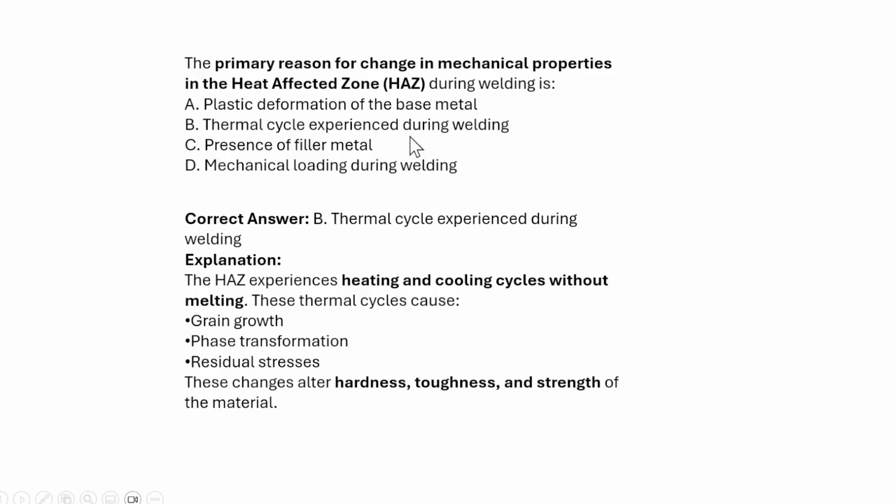Thermal cycling, yes, the heat dissipating from the fusion zone will affect the microstructure of the base material. Next is the presence of the filler material. No, filler material is not the reason. Filler material is present at the fusion region, but it is not effective here. And mechanical loading during the welding: we are not providing any mechanical loading, so that is also not the reason. So the answer is thermal cycling experienced due to welding. The HAZ experiences the heating and cooling cycle without melting.